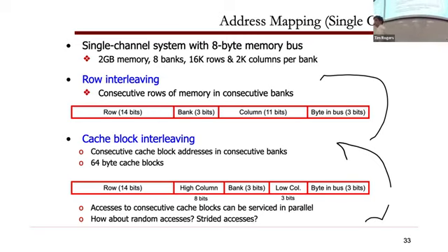Okay, other questions? The byte in the bus, is that stored across multiple different chips, depending on like the 0th chip? Yeah. So I've abstracted away the concept of a chip versus rank here. I'm assuming that this is just one big wide rank, essentially, right? This is like a big chip, the way that I've described it, where you can get 8 bytes out at a time.